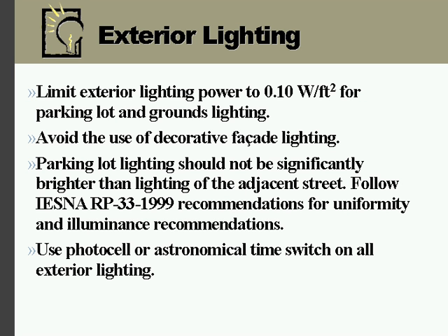Exterior lighting, again, one of the bonus savings is exterior lighting. Eric went through the ASHRAE recommendations for exterior lighting. Here we're saying limit exterior lighting power to 0.1 watt per square foot in the ASHRAE standard if you are lighting the building grounds, walkway, pathway, those types of areas. It's 0.2 watts per square foot, so about half the lighting power density. In parking lots, the ASHRAE requirement is 0.15, so we're still 2/3 of the recommendation of the ASHRAE 2004 standards.